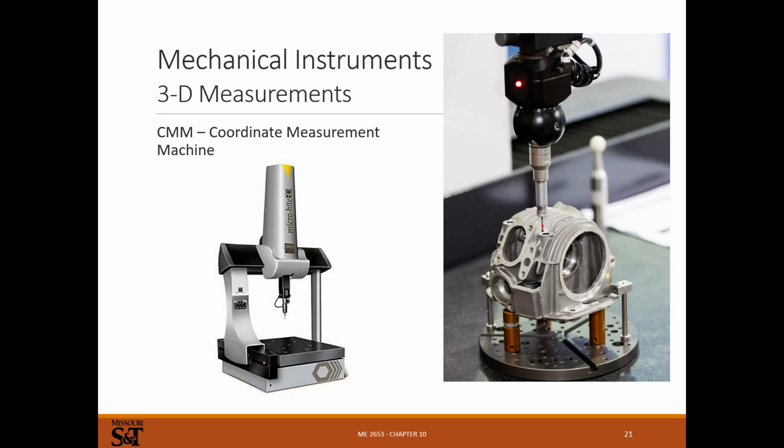They'll measure the distance you've moved this way, this way, and this way, and then the probe will detect where you've contacted on the sphere. From the measurements of the slides and the measurements from the probe, it can figure out where the point you touched is in three-dimensional space. So this one would be manual. You'd move it all around.